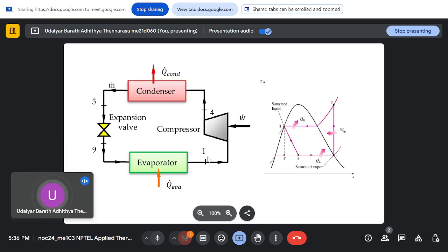So with that, next we saw was vapor compression cycles. So vapor compression cycle again is similar to a Rankine cycle, but you are running it in reverse, and instead of your isentropic expansion, you use an isenthalpic expansion. So it's simpler because you cannot handle two phase.